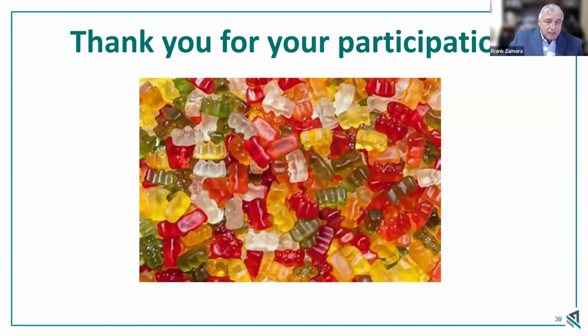Cationic systems are good. They have their applications, and the Northeast runs a tremendous amount of cationic FRs. In some cases, a cationic will stay cationic for a period of time, and then it will actually convert over to anionic. Depending on the FR type, I'm not saying they all do, but some of the ones we've seen, you have to worry about that to make sure that it doesn't go from a cationic to an anionic, and then you run stage two. Stage one has already gone into an anionic mode, and you have communication between a cationic and anionic FR. Now you've got yourself another problem, but it doesn't always happen.